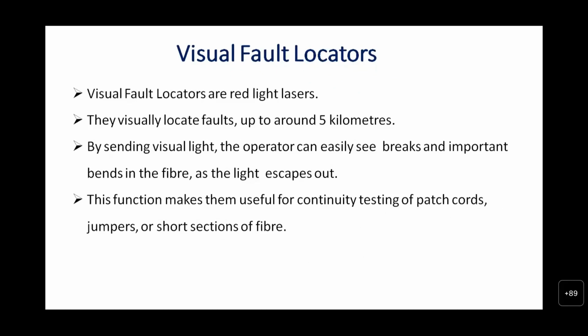As far as the OFC visual fault locators are concerned, a red light laser will be used. They visually locate faults up to 5 kilometers. By sending visual light, the operator can easily see the break and important bends in the fiber as the light escapes out of it. This function makes them useful for continuity tests of the patch cords, jumpers, and short sections of fibers.